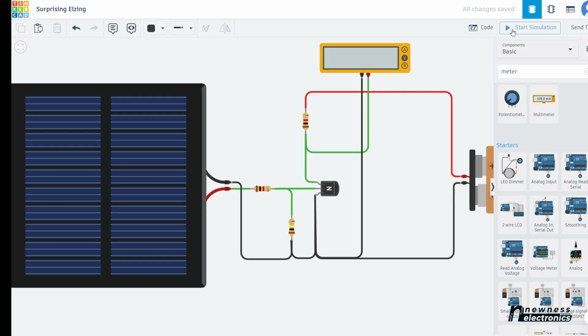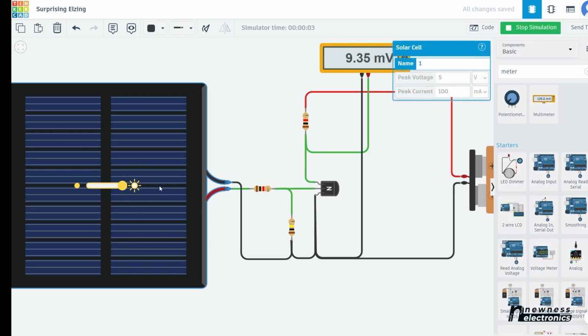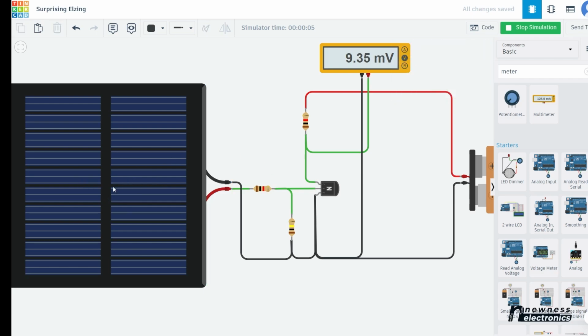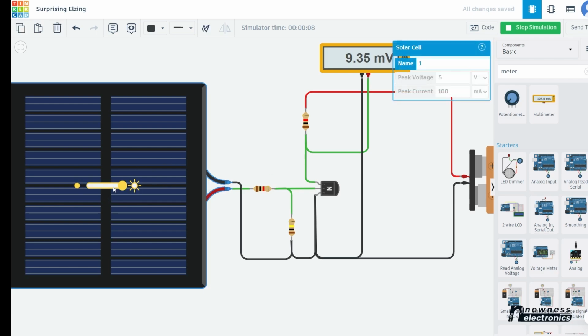Now, when we start the simulation, this is when the transistor is on. At full brightness, the voltage between the collector of the transistor and ground is almost 0 volts. Do you know why? It's just as though there's no resistance across this transistor. Very low resistance. So the resistance is almost 0 and therefore there's no voltage drop across this transistor.